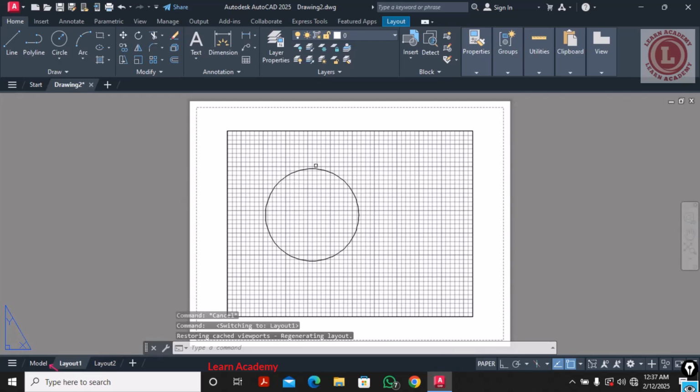This is where we prepare the drawings, add our title page, the name, your name, the scalings, and every other piece of information before we print out. On this layout space also, you can set whether you want to print, and you can even change the size of this layout to either A4, A2, A3, as the case may be.